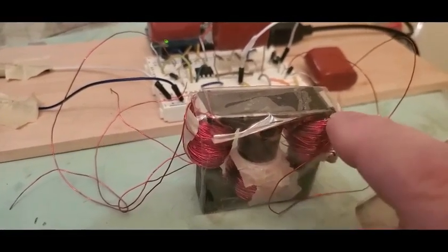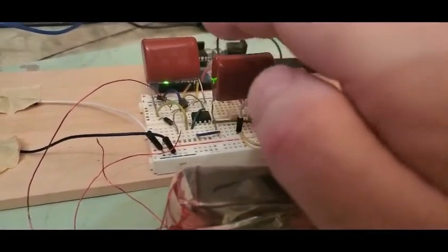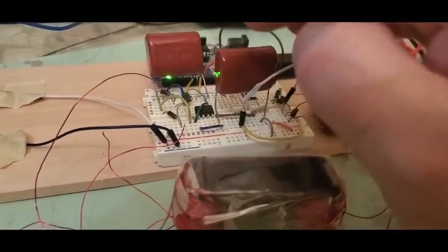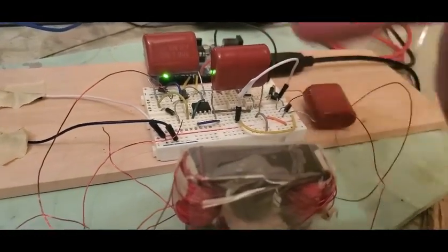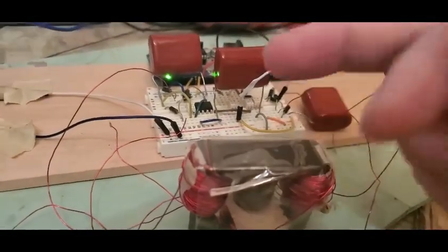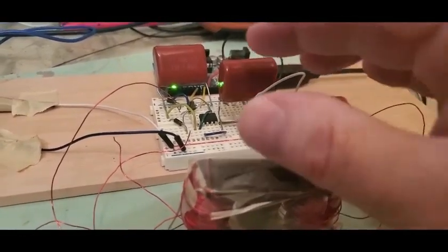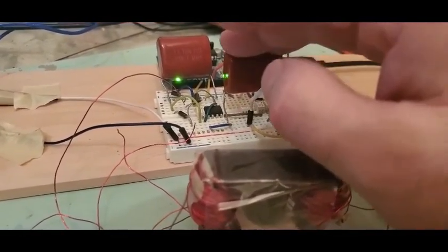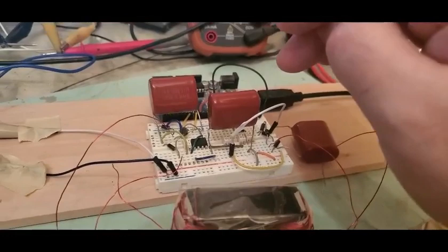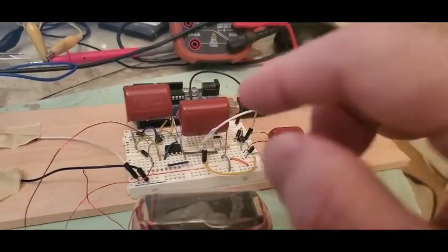And since the current is flowing in the opposite direction, it puts a negative voltage now into the cap. If the cap and coil were perfectly undamped, then the capacitor would go to negative 10 volts, then it would discharge, and the current here would be 0, and they would just keep going back and forth in perpetuity. In general, there's usually some dampening where this will go from 10 to, say, -8 or -9, and then back to +7, +8, and it will ring for a while like a bell,